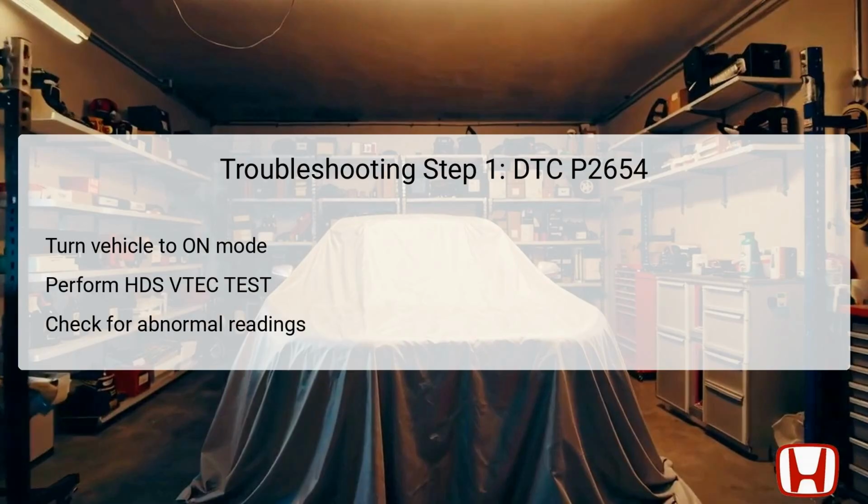This test is crucial as it checks the operational status of the VTEC system, which is directly influenced by the rocker arm oil control solenoid. Monitor the HDS display closely for any abnormal readings.